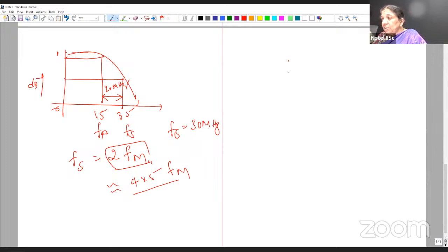In excess addition, we can only go up to 40-bit. For a 32-bit word, we have 8 extra bits, which we call guard bits in the architecture, so they can take overflow up to this limit. I can do 40-bit addition, not more than that.